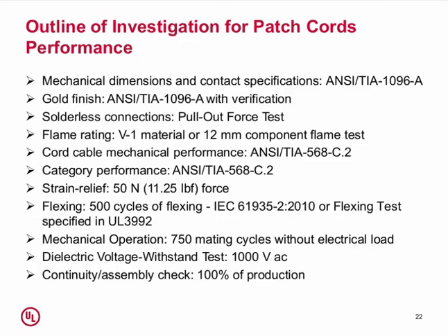The gold finish and the plating processes and the verification also come from TIA 1096A. There's the requirements for the type of gold, the thickness of the plating, the nickel base material, things like that. The solderless connections is an interesting one. There's a number of IEC standards that deal with all the different types of solderless connections that you might see. And what we found was that from a manufacturer's standpoint, it's a good idea to use those specifications, but the testing and the evaluation involved in meeting all of the requirements was just too onerous for what we were trying to do with the specification.